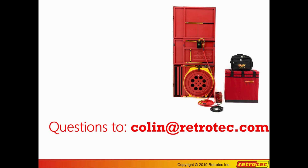Someone was asking about whether the door fan test is only done once. In fact, both the ISO and NFPA standards require an evaluation to be done, I believe, on an annual basis, and if any doubt exists, the door fan test has to be repeated. I know in some jurisdictions this is not done, but in Korea, for example, they do repeat the test every year.